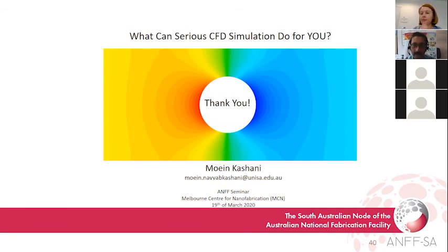So with a small scale of the slurry, we assume that it's Newtonian flow. So we haven't included the non-Newtonian, but it doesn't mean that we can't do this. We didn't do this because the main interest of that simulation was letting the ion penetrate through the diffusion window and sensing, but not the particle. So the condition of the slurry was not very obvious for us and was not very relevant to our study.